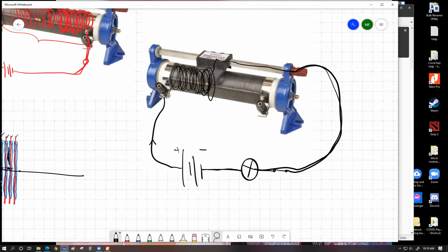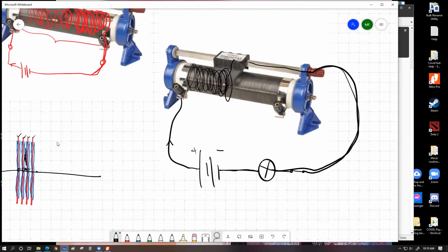Does the pathway sound acceptable? Why could the current actually enter through the copper teeth? That's why I tried to explain that by the rubbing of the copper teeth, a little bit of insulation of the resistance wire gets removed. Through those contact points, the current can actually travel from here and eventually travel up there and eventually go out and come back over here.